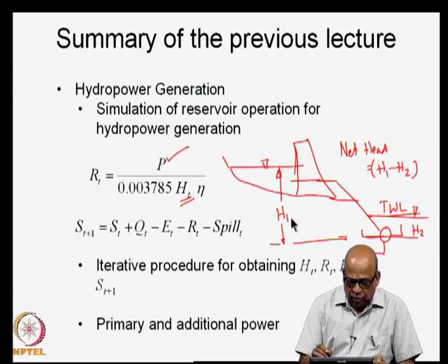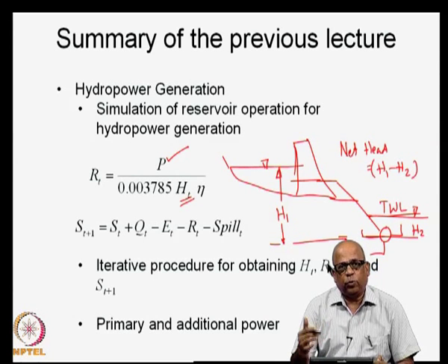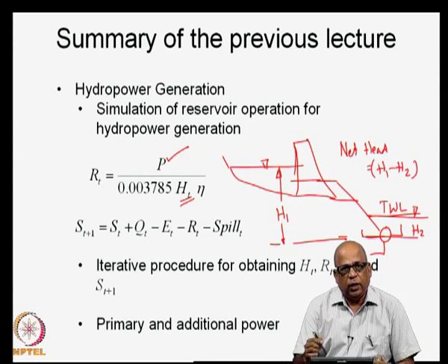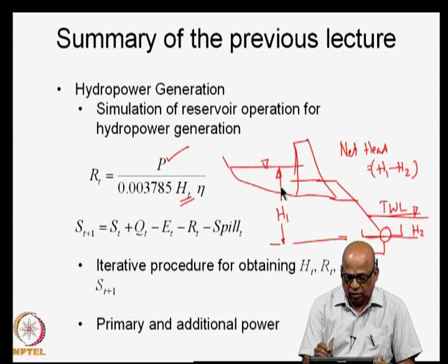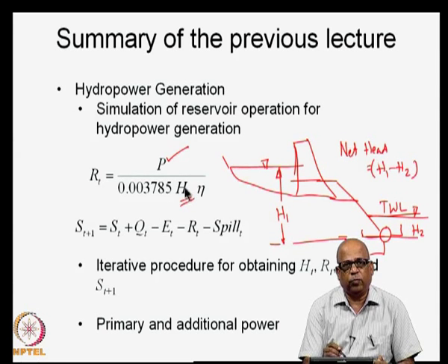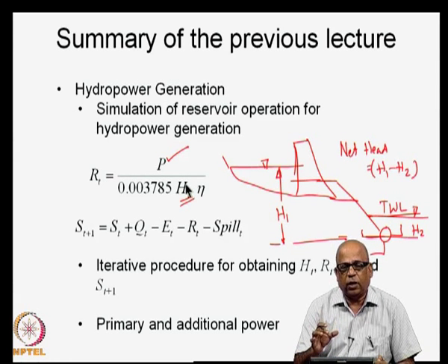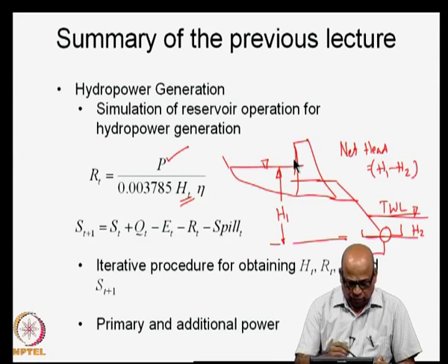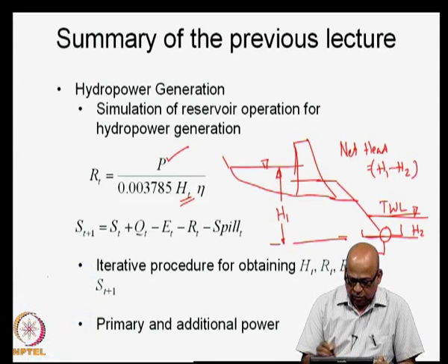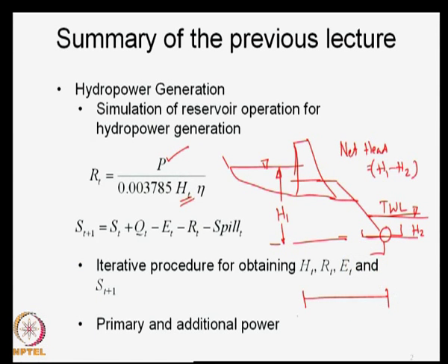And then we introduced an iterative procedure, because the total head depends on the storage. So, HT, which is the net head during the time period T, will depend on the storage at the beginning of the time period T, ST, as well as the storage at the end of the time period, ST plus 1.